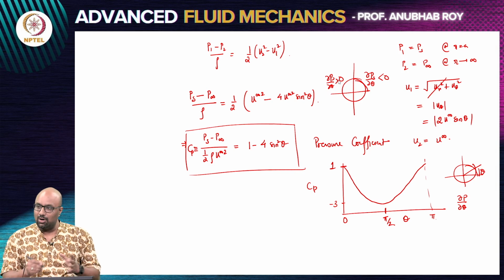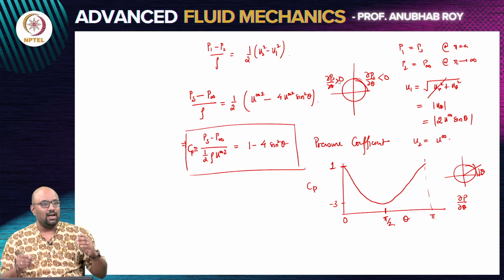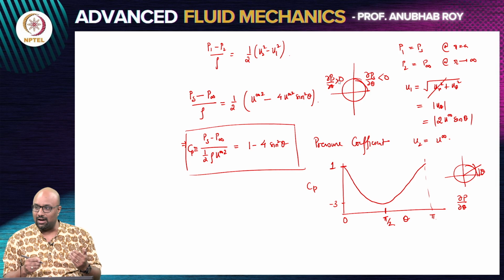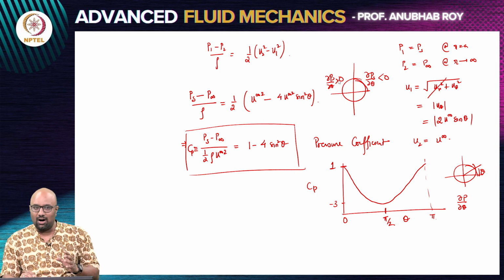So, we were actually able to do a calculation where we have never said anything about not doing a nonlinear calculation. We are not doing some very simple geometry. It is a circular cylinder in a uniform flow. It is quite complicated. If you take a step back and think what you have here, the velocity field and the pressure solution that you have obtained, it's not a trivial calculation. But the ease of how we do things when you say it's potential or irrotational allows us to do this in quite simple terms. So, we don't stop exactly here, we still have one more thing to do.